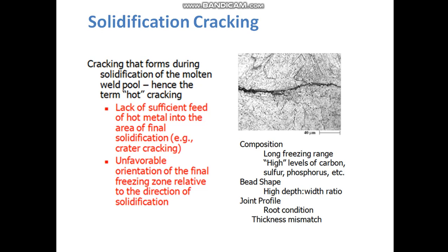It is an unfavorable orientation of the final freezing zone relative to the direction of solidification. So the liquid hot metal cannot feed the small crack that forms.